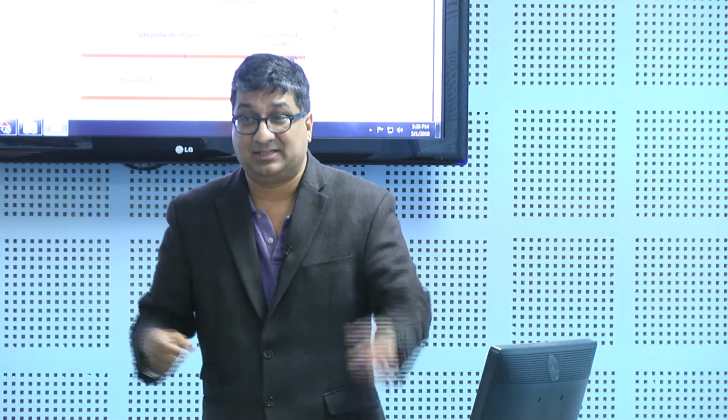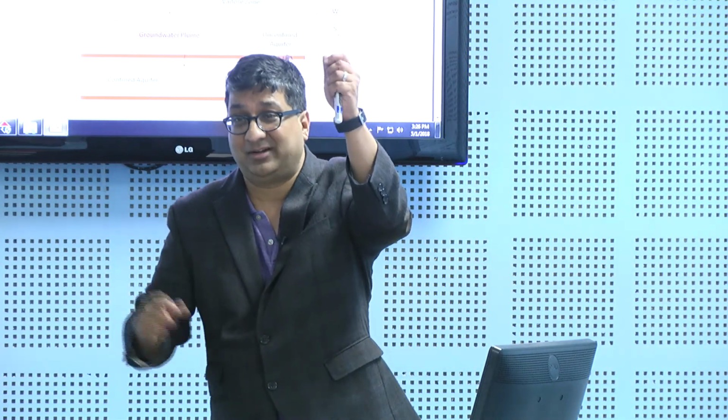my concentrations become low and low and low, the treatment efficiency becomes low and low and low, so it's harder to remove. It's easier to remove the first molecule of the pollutant than it is to remove the second molecule of the pollutant, and it's even tougher to remove the third molecule of the pollutant, so on and so forth. So that's just the way our treatment works, because all our treatment technologies are driven by some concentration gradient. If the gradient is low, our treatment flattens out, right?